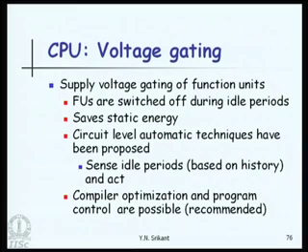They see how many cycles the function unit has been idle, and based on that the algorithm switches off the supply voltage to the function unit. So, let us say 2 cycles of inactivity trigger switching off of the supply voltage, and it remains in that state until the function unit is required again.